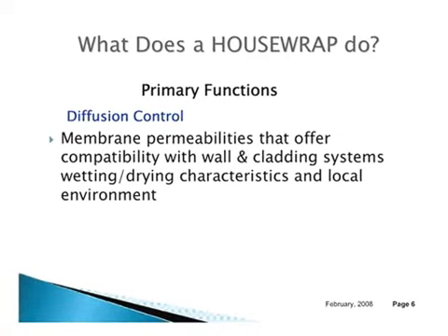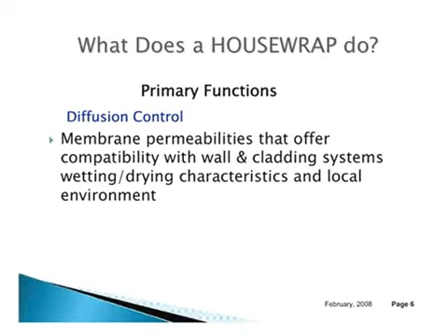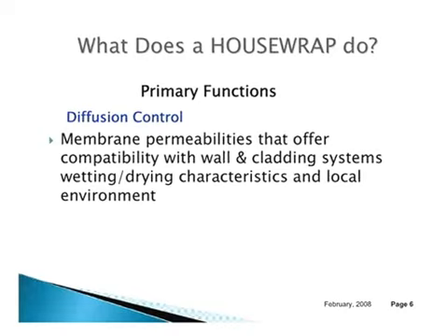The other function it provides is vapor diffusion control, and it allows walls to dry. So you're not going to run into any problems with a buildup of moisture within the wall assemblies. And you're going to be able to combine Housewraps with a wall assembly, which will allow, in that particular environment, for it to be able to dry to the outside.